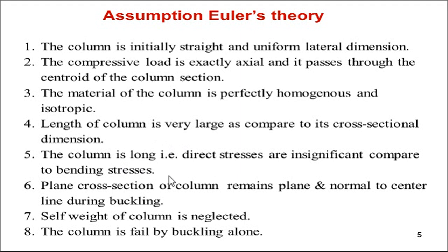The column is long, so direct stresses are insignificant, very small and negligible compared to bending stresses. Bending stresses are important because the major stresses induced are bending or buckling stresses. Direct stresses are very negligible, so they are insignificant for a long column. Plane cross sections of the column remain plane and normal to the center line during buckling. So the plane cross section before buckling, during buckling and after buckling remains the same.